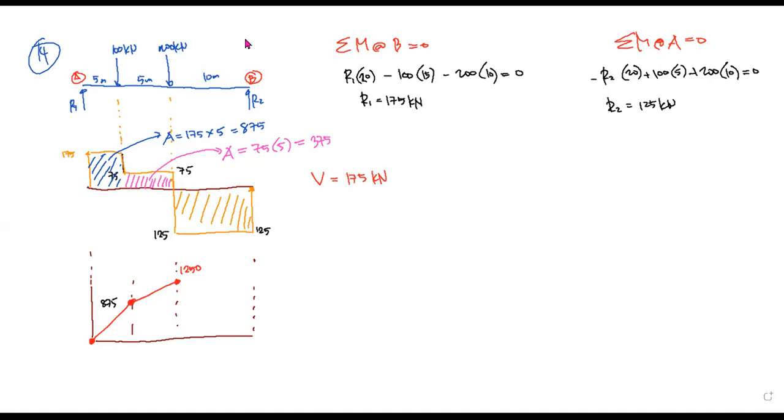And then considering the fourth area, this one, okay. So area here would be equal to 125 multiplied by 10. Okay, so the length is 10. So you have there 1,250. Since this is located at the bottom, this point here will be subtracted by this area. So 1,250 minus the area below the reference line would be equal to 0. Okay, so again, you will know that you got the wrong solution if you do not end up with 0.